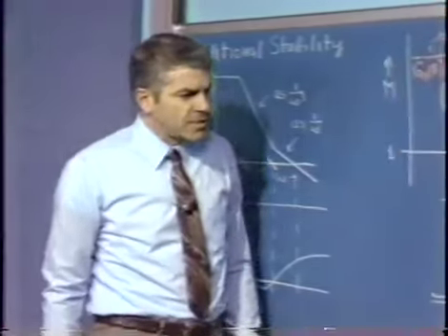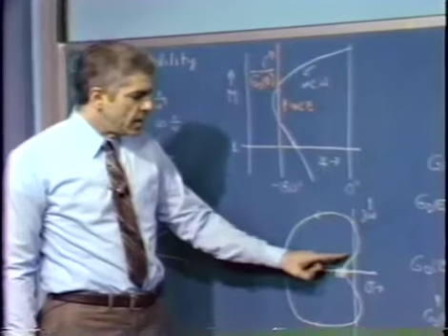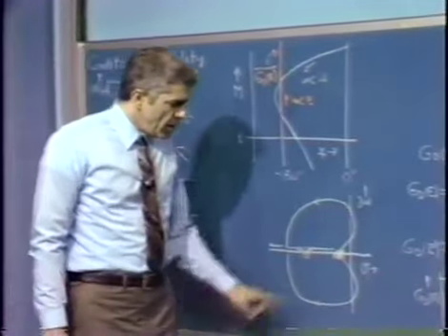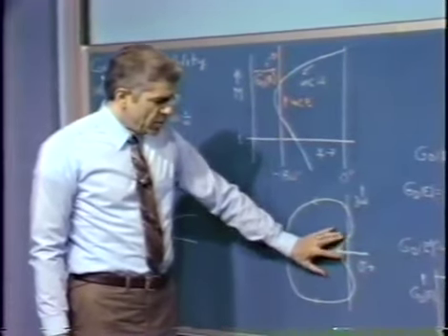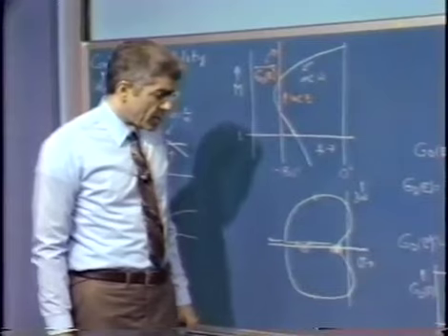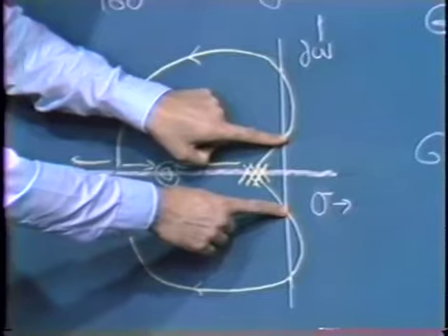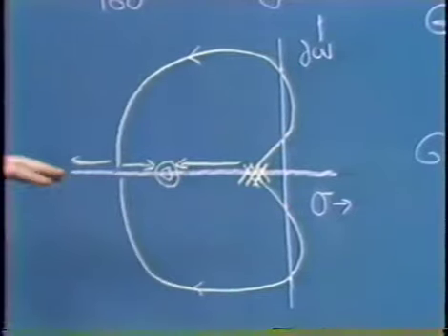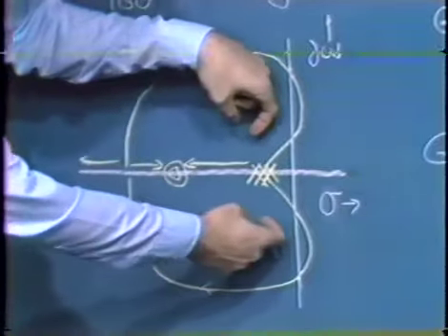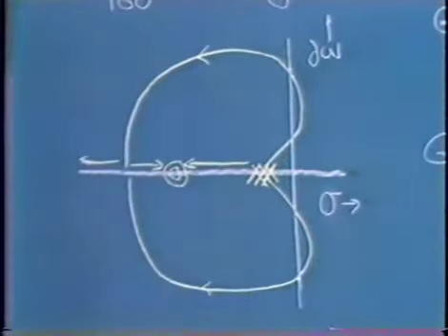Again, we can make the same exact kind of argument, and I think it's worth comparing these cases, in a root-locus presentation. Suppose, for example, we had the correct amplitude so that when we considered the gain of the nonlinearity, the describing function for the nonlinearity, our pair of closed-loop poles was precisely on the imaginary axis. If we assume a slight increase in that amplitude, the magnitude of the describing function decreases. We move back in the left half plane. The system's stable. The amplitude shrinks back to its original value, and so forth.